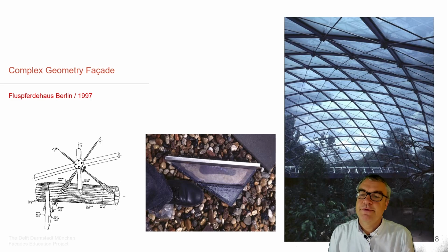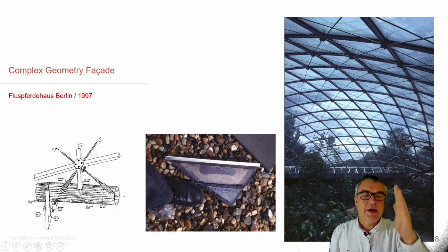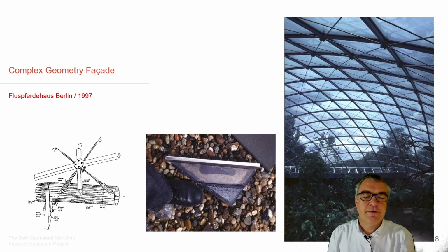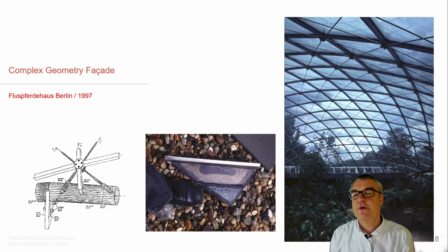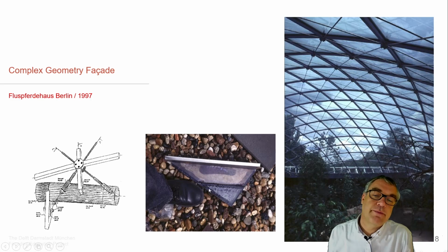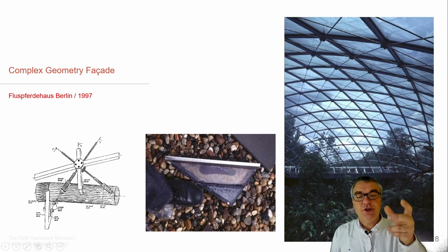That's what they solved with a huge profile. You rarely see it here at the edge. A huge profile which takes down all the components of the grid shell structure and then takes the load and then transfers the load to the foundation, to the base. That can be done in steel as a system, but we also can envision that this at the edges creates an interesting shape of glass plates, and this is an IGU unit with a super small triangular IGU package.